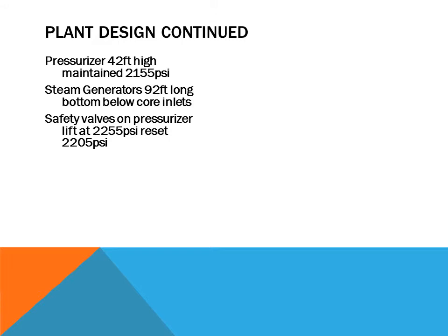Design features and some other problems within their reactor plant prevented them from understanding what was going on. These valves are critical to prevent the overpressurization of the reactor, though, past design hydrostatic test pressures, and prevent it from rupturing. Inside the containment building, there is a pressurizer relief tank. The pressurizer relief tank accepts the water that comes out of this pilot-operated relief valve, or the safety valve on top of the pressurizer. This relief tank allows the water collection, therefore preventing it from spilling out into the containment building and then later into the environment.